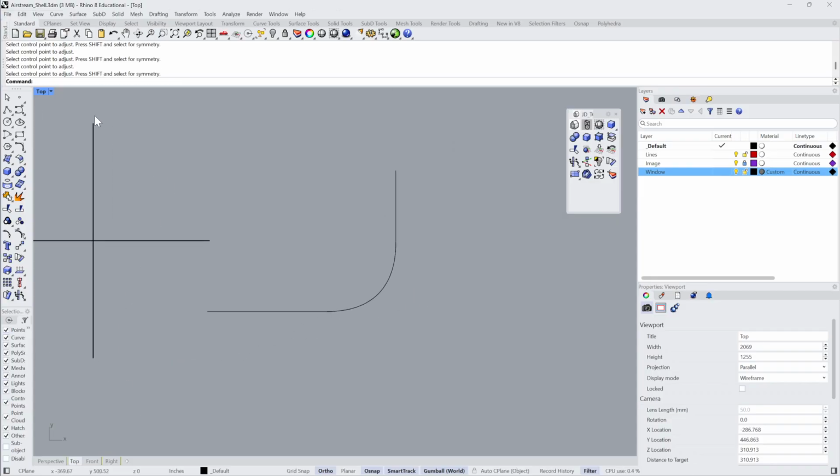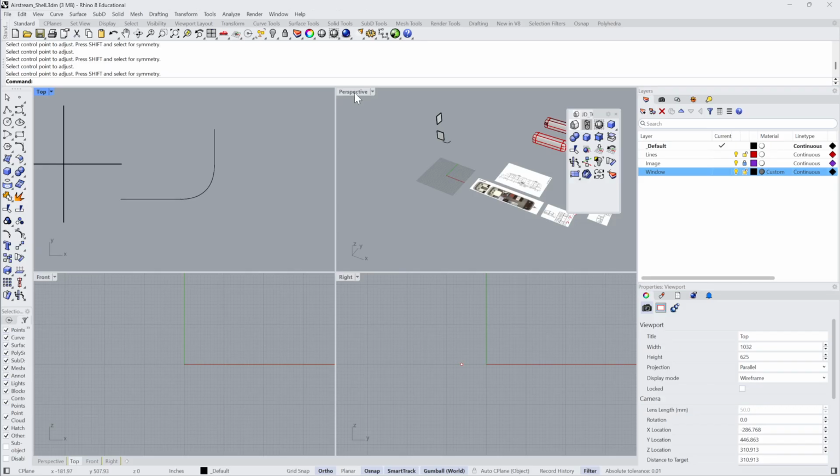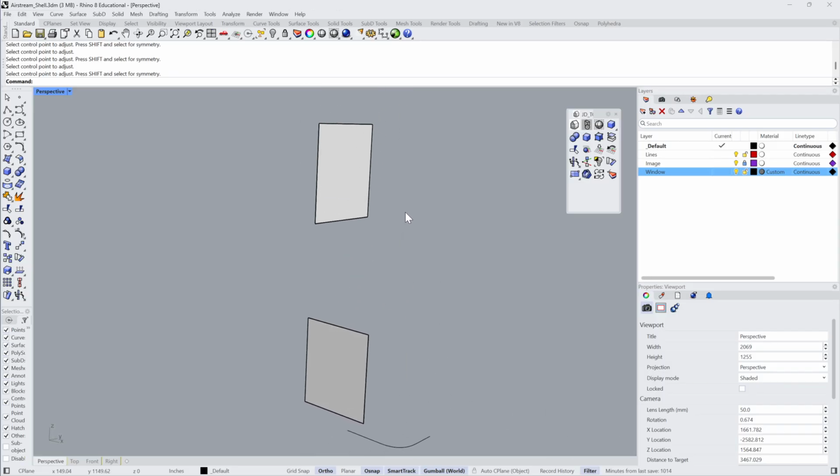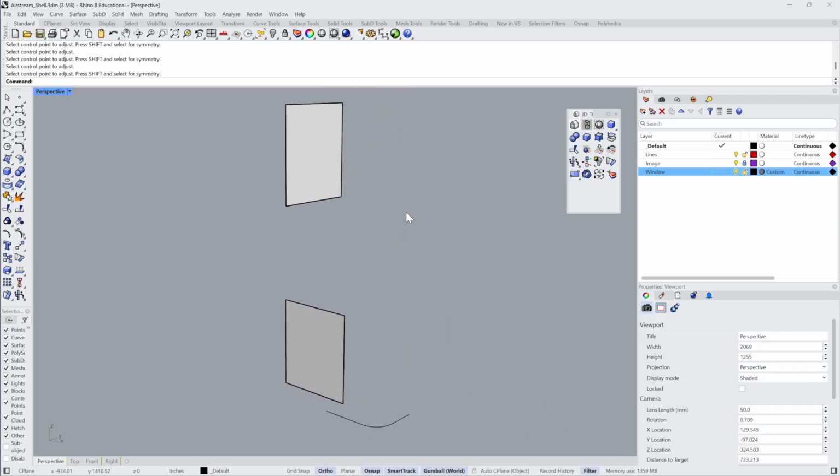And then, of course, we also have the related blend surface. And this is really useful, and not all of our students know about this. So the first one was blend curve. Now we want to do blend surf. And we need to pick corresponding edges here.